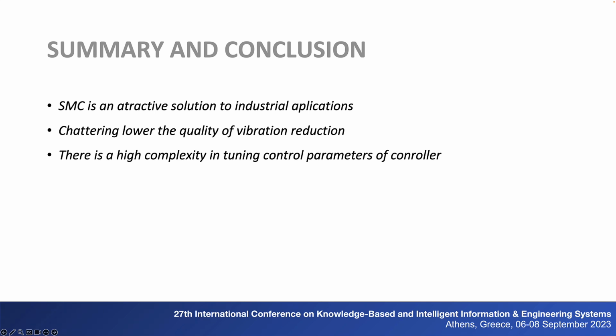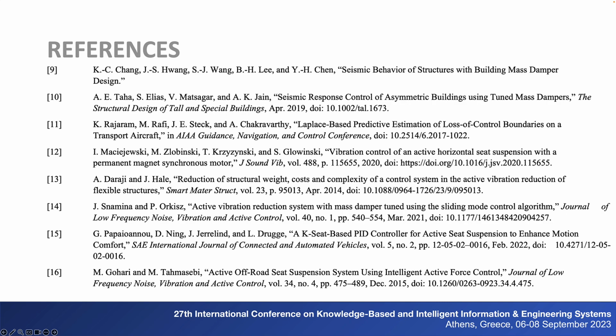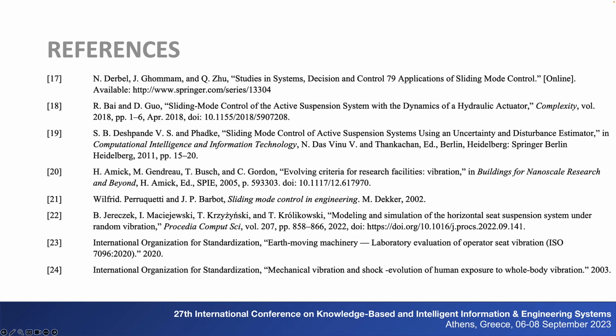The sliding mode controller is responsible for sending feedback signals to the PMSM motor in order to generate the force required for keeping the system under specific control conditions. The SMC can effectively handle these disturbances and ensure passenger comfort. The SMC has a simple implementation, requiring few or no additional sensors, making it a cost-effective solution. This simplicity makes the SMC an attractive option for industrial applications.